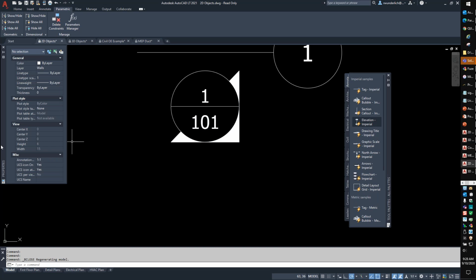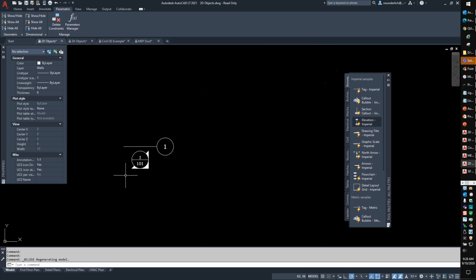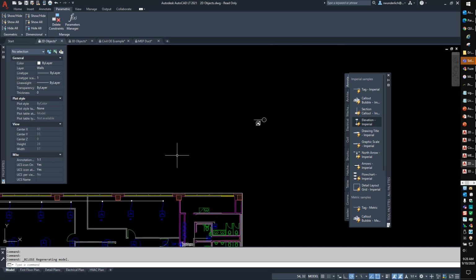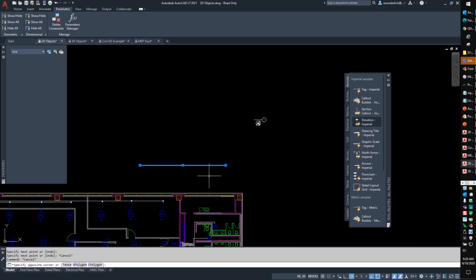All right, in LT, how do you add a Z coordinate to the point at an end of a line? That's a good one. So we want to draw a line. There are really two ways of doing this. You can draw your first line here, and you'll see that we have properties, and I can change my Start Z here to 20.